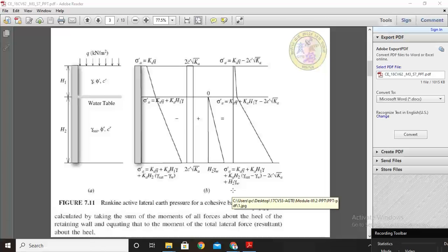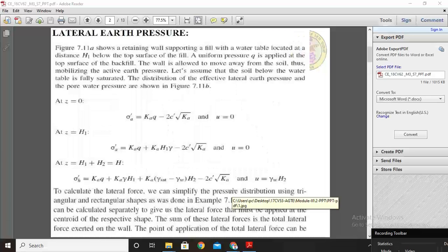You should remember this technique. Here we are calculating the lateral earth pressure at the base for the given condition with respect to height into density of soil, multiplied by the coefficient of active earth pressure. This is the simple calculation or logic. So that is explained here, clear.